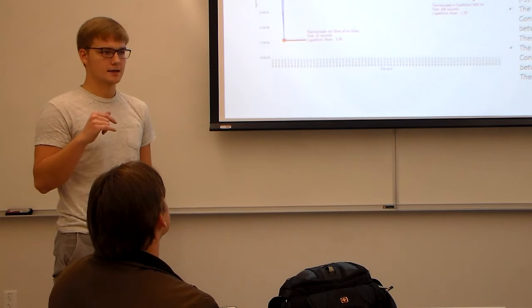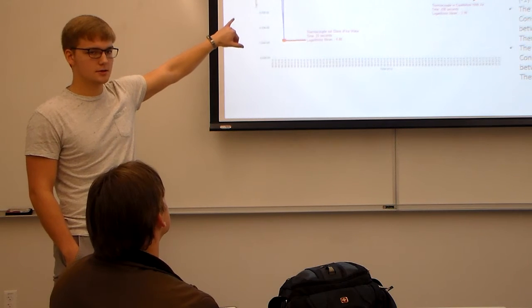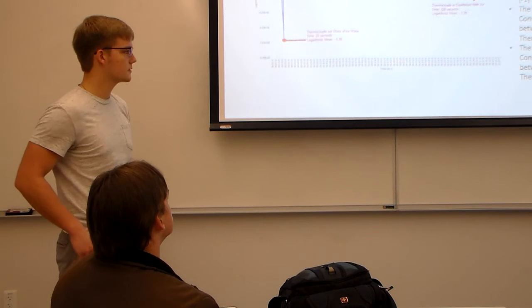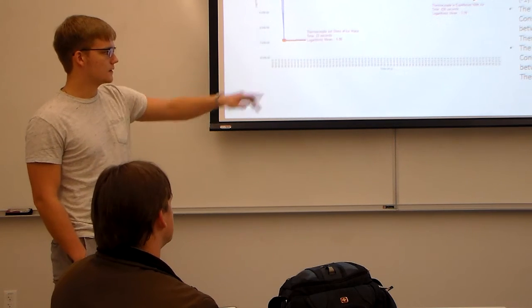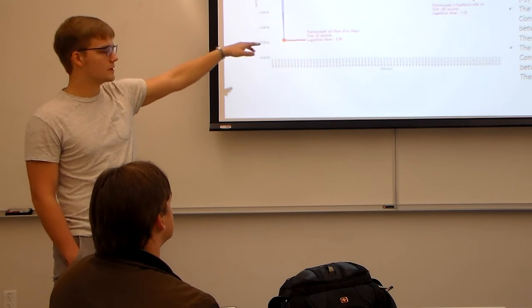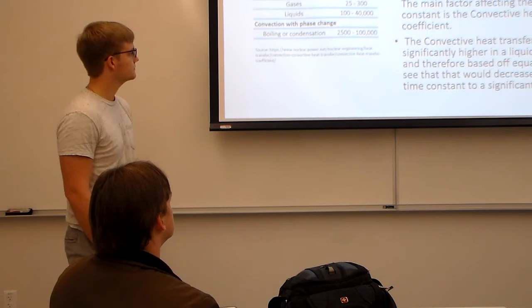Because we're expecting a linear change, I took the boundary conditions and did the average slope rather than doing the curve fit, which describes basically the average slope. And I did the same thing for the thermal time constant between it warming up from the air, and I got 135 seconds as our thermal time constant.